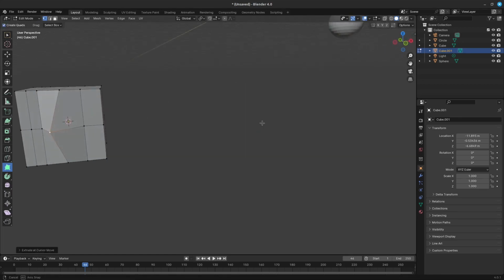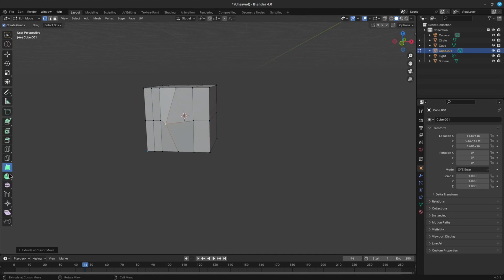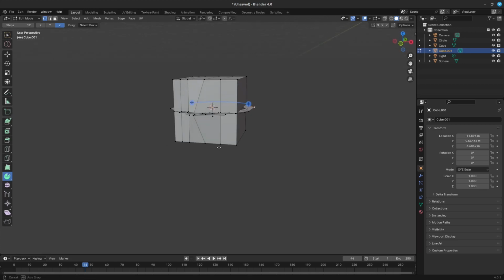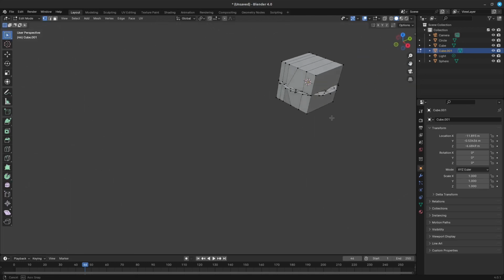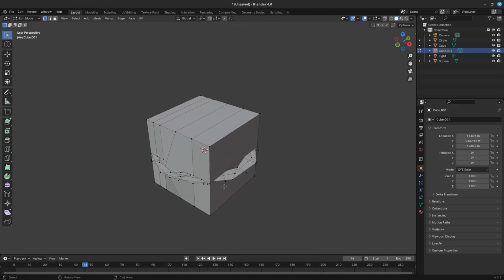And lastly, since we are talking about tools and extruding, if you have a shape and you need to spin a section, the spin tool is your guy. The spin tool extrudes, or duplicates it if the selection is manifold, the selected elements, rotating around a specific point and axis. Use the tool to create the sort of objects that you would produce on a lathe. This tool is often called lathe tool or sweep tool in the literature, for this reason. In fact, it does a sort of circular extrusion of your selected elements centered on the 3D cursor and around the axis perpendicular to the working view.